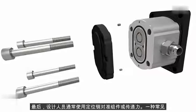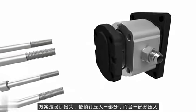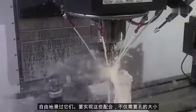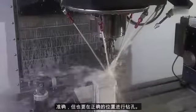Finally, designers often align components or transmit force using dowel pins. One common scheme is to design the joint such that the pins press into one part and then the other part freely slips over them. Achieving these fits requires not only that the size of the holes be accurate, but also that they are drilled in the correct locations.